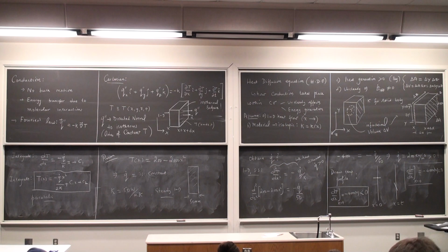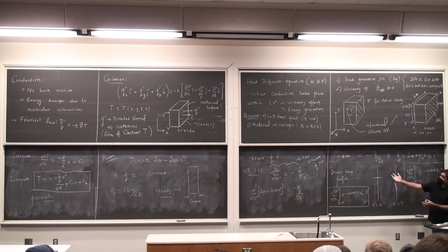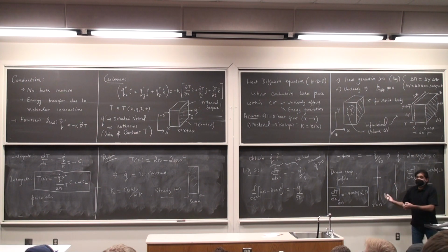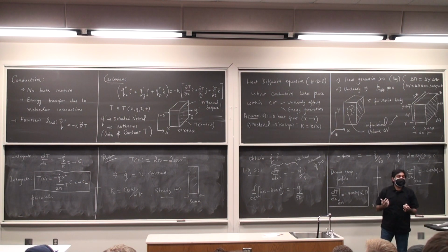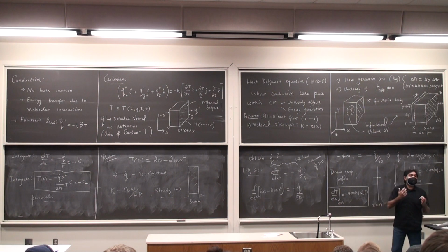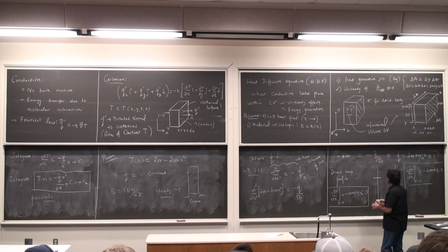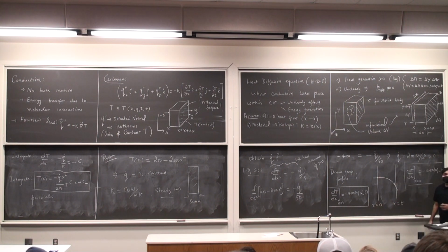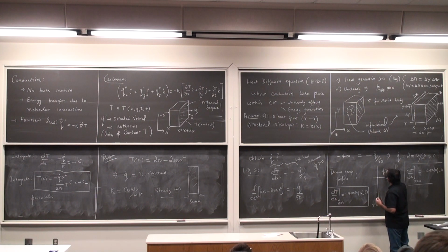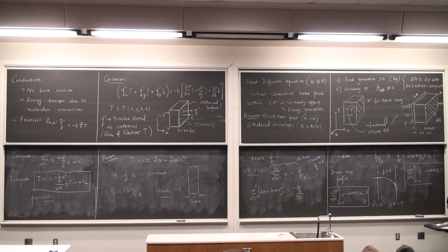And so the direction of heat transfer is quite easy to understand by just substituting. At x is equal to 0, temperature at the left hand side is 200 degrees Celsius. At x is equal to 50 millimeters, temperature at the right hand side is 195 degrees Celsius. It is going to go from left to right, and the profile of the temperature distribution is going to be parabolic, and this is for Q dot greater than 0.